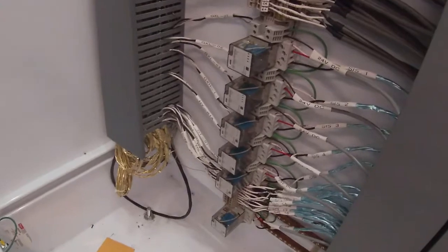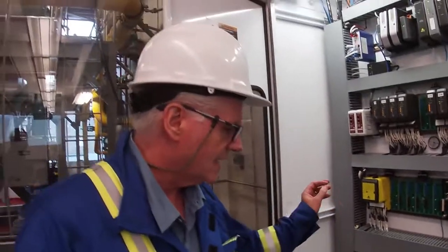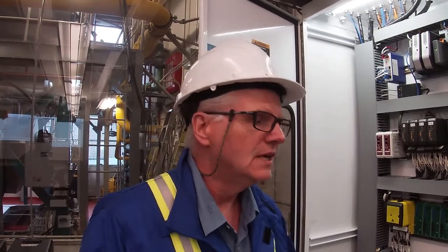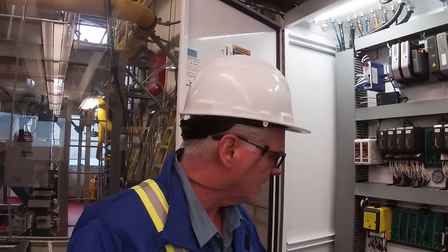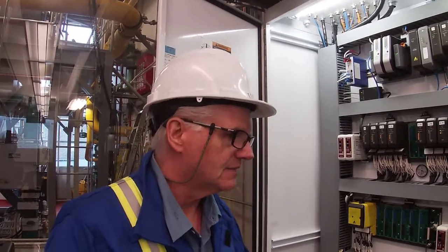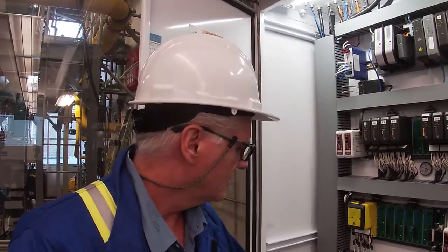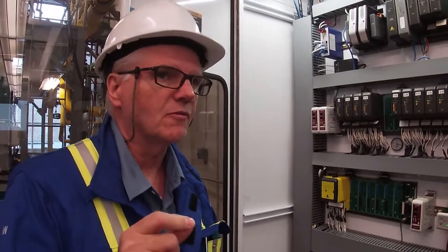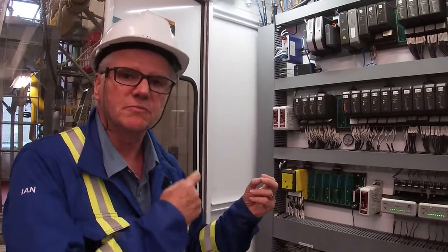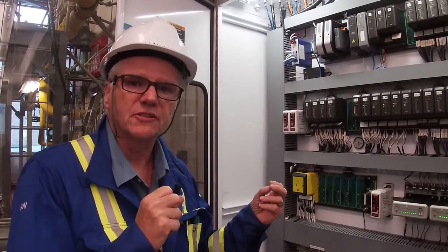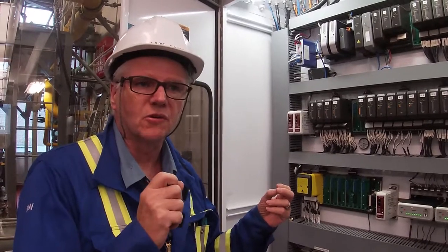Now, the reason that those relays are there is because the SLS module tests the integrity of the loop. And so every so often it'll just pulse an output. And what we found was that there was enough current going through the loops that, for example, if we had a horn or a strobe in the field, sometimes the pulse would be picked up in the field and you'd see the strobe flash once, or you'd see the horn just beep.